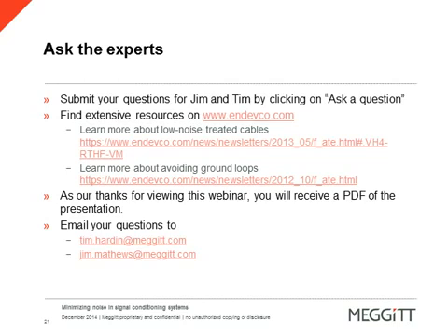What kind of material can we use in order to isolate the accelerometers? Well, this is Tim, but primarily you would want to use something that's qualified for the application, meaning an isolating mounting stud is the best method to couple all of your energy. It is designed to mate to the sensor, be it adhesive mount, be it 10-32 stud, whatever the type of application is. That is the best technique to use because, again, you want to couple all of the energy as well as eliminate the noise.